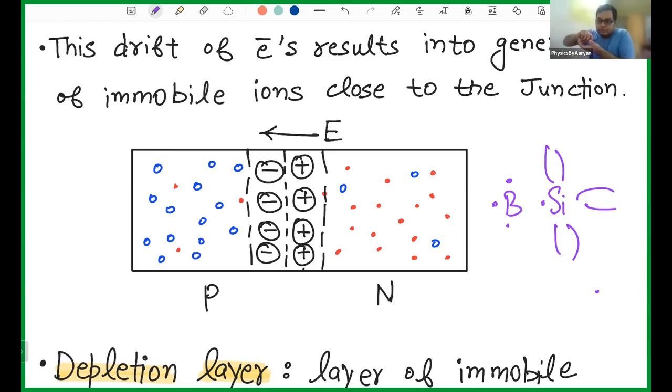Electron is not missing. It means he does not have an extra electron. However, his own electron is not missing. Boron is born with 3 electrons, so none of his electrons are missing. But as he grew up, he saw that if I would have one more electron somehow, I can make a bond with him. So that desire to have one more electron, which he does not have, is a hole.